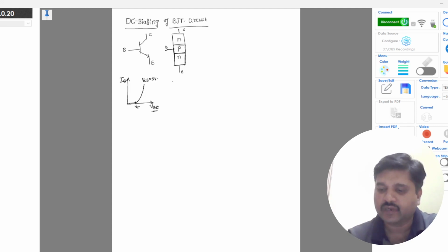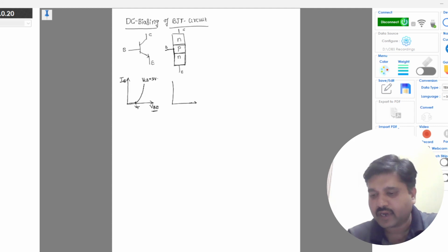on the device. And for the output characteristics, we vary the output voltage and we observe the output current, keeping the input voltage constant, somewhere a little greater than the threshold voltage. That is the minimum voltage that we keep here. And when you vary the output voltage, the output current will be something like this.